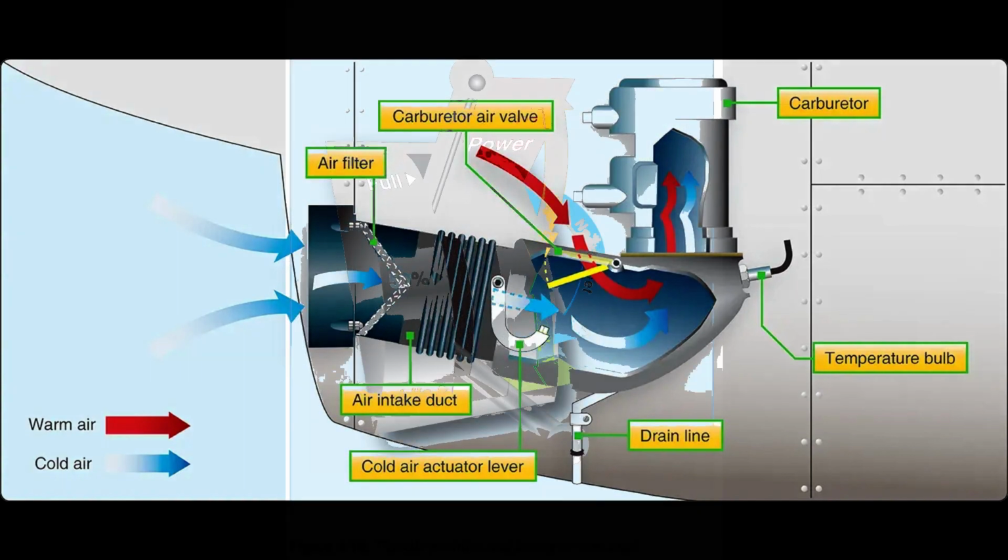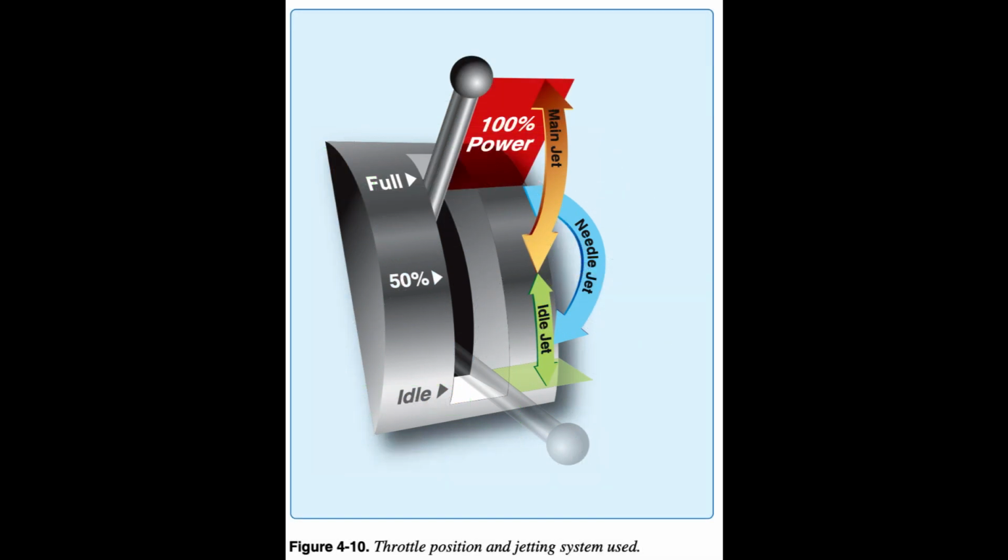Carburetor systems. WSC aircraft use float-type carburetors. The float-type carburetor acquires its name from a float that rests on fuel within the carburetor float chamber, commonly known as the fuel bowls. The float maintains the fuel level in the fuel bowls. As fuel is used by the engine, the fuel and float levels drop, opening the valve, letting more fuel into the fuel bowls until the proper level of fuel in the fuel bowls is achieved and the valve is closed.